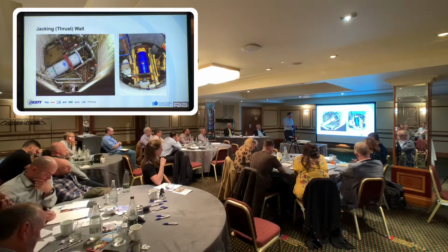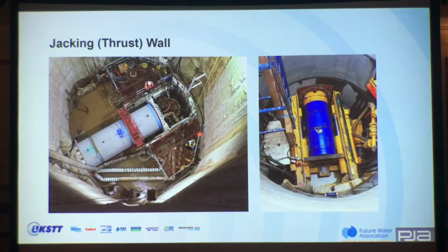So just a couple of examples. In this instance the loads are small, so the back plate is sitting on the lining, and this is a diaphragm wall shaft, a big D wall shaft, and you've got a concrete back wall on the back there. Again, this was about 1200 mil thick, so inherently the diaphragm walls have got a lot more in the way of robustness, should we say, for the jacking loads. I think that one was designed for something like a 1200 ton jacking load.